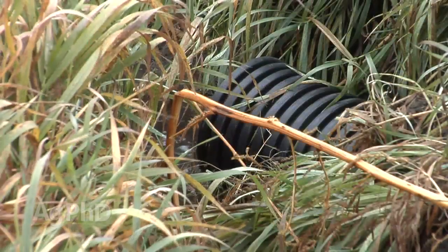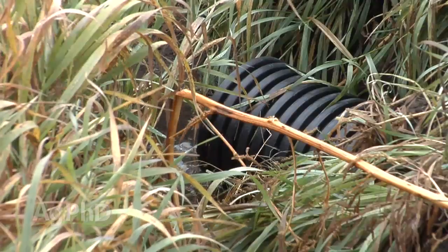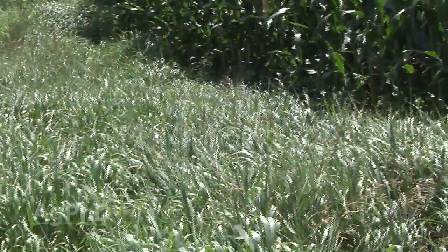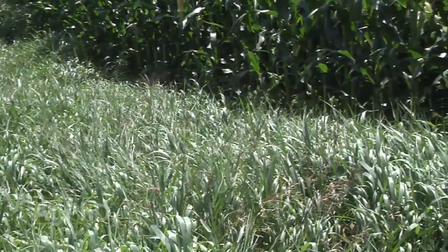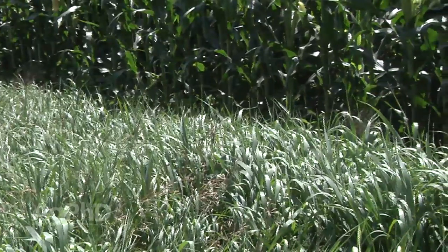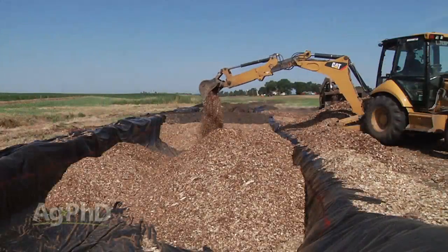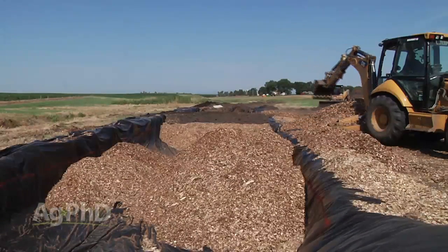Well, the other thing is when you're outletting that tile water, if you outlet it into a grass water strip or you outlet it into a buffer area where you've got some room where you can try and absorb some of those nutrients, a place for any soil that may have gotten in there to get filtered back out. We've even got a bioreactor with wood chips on our farm to try to filter out any nitrates that are in the water, and it's been fantastic.